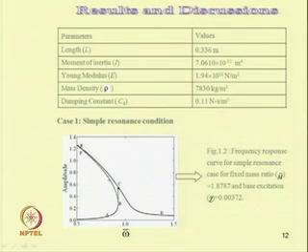When we sweep up the frequency, up to B the system is stable, so it will follow this path, that is A, B, and at B with further increase in omega bar, the system will be subjected to a jump up phenomenon, and then one can get the stable response of the system.